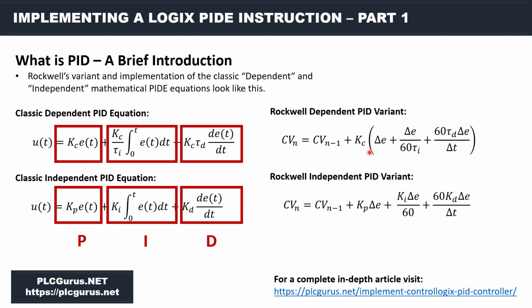And that is convenient for us because now once we've set up the P, the I, and the D, if we're implementing a full PID control, which we don't have to do, there are P-only control. I mean, there's drawbacks to P-only, of course. There's PI, and most implementations in industrial processes are P plus I controllers or PI controllers. And then, of course, there's full-blown PID controllers. And this is where you get into servo motion, this type of thing, okay? So we're going to be implementing it as a PI controller. And maybe when we get into some auto-tuning, we will see that it actually adds a little derivative action in there for us in an auto-tune procedure. But we'll take a look at that. We're going to go baby steps here.